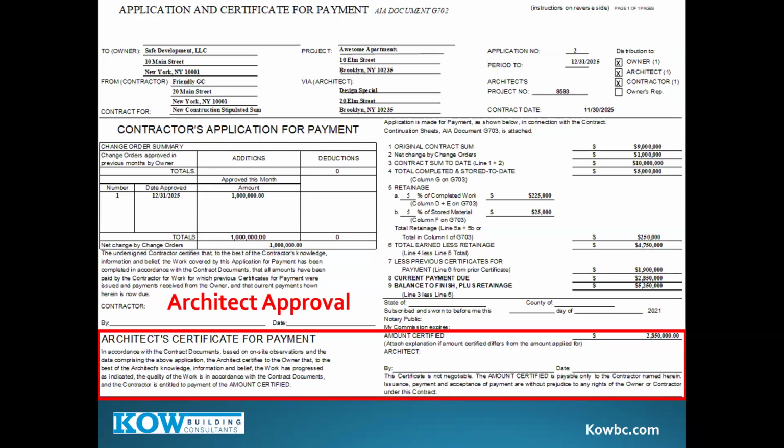Does an architect have to sign every project? No, depends on their role. Most projects, the architect, or better named design professional, because it could be a professional engineer. Most cases, the architect will sign this throughout the project. When don't they? I'll give you a heads up. It's when you have a project that an owner is the contractor. So if you have one entity essentially that is the owner and the contractor, they often don't have the architect sign this because they don't need to police themselves via the architect's signature. They save the money. They don't need them to do this.